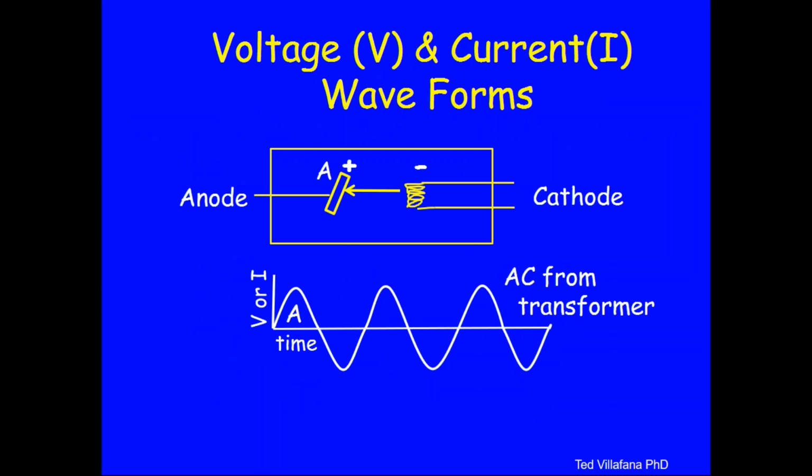Well, that presents the problem that needs rectification. Here you see electrons going from the filament to the target, negative to positive. That's good. That's how we get high energy electrons, and that's how we get our X-rays produced. But that will occur during one part of the cycle, the positive half of the cycle. Now, what happens when the AC goes to the negative half, the B part?